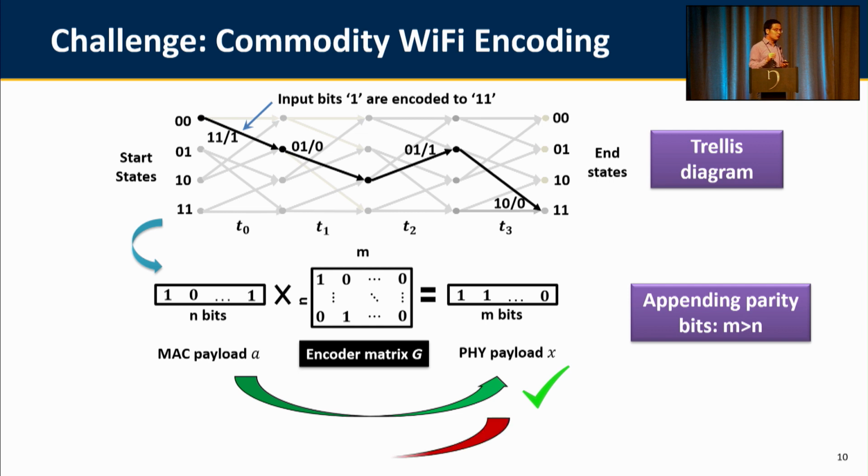However, when we are trying to reverse this procedure, so that given a physical layer payload we compute the corresponding MAC layer payload, it's equivalent to pruning some bits from the given code word. So this cannot always be done, and there is a possibility that we select some constellation points for emulation, but then we find out that we cannot reversely compute the corresponding MAC layer payload.